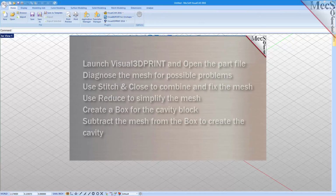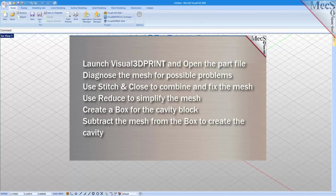Okay, before we get started, let's go over the steps we're going to take. First, we're going to launch Visual3DPRINT and we'll open our part file. Then we'll perform a diagnose on the mesh and see if we got any problems. Then we're going to use stitch and close to combine and fix the mesh. Then we'll use reduce to simplify the mesh.